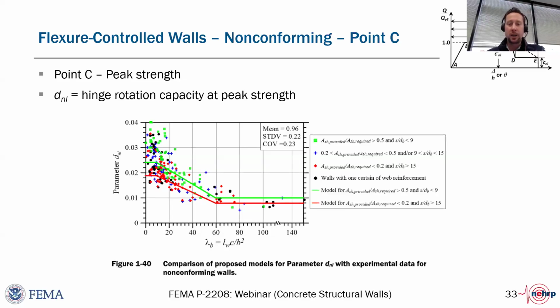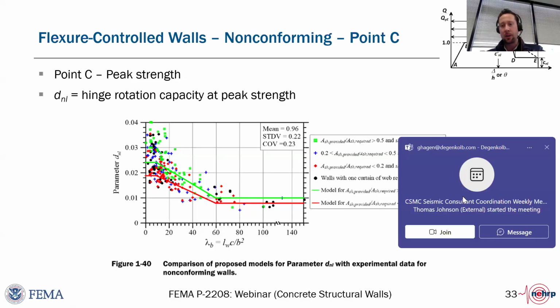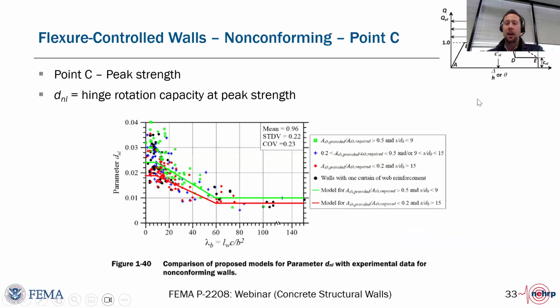So it's worth mentioning in case you're considering your fiber model, and you do have the ability to use an overstrength on the steel to account for this. The provisions and the recommendations talk about that, but it's actually permitted to use just a factor of 1.15 on your calculated moment strength, and that's the reason that's permitted.